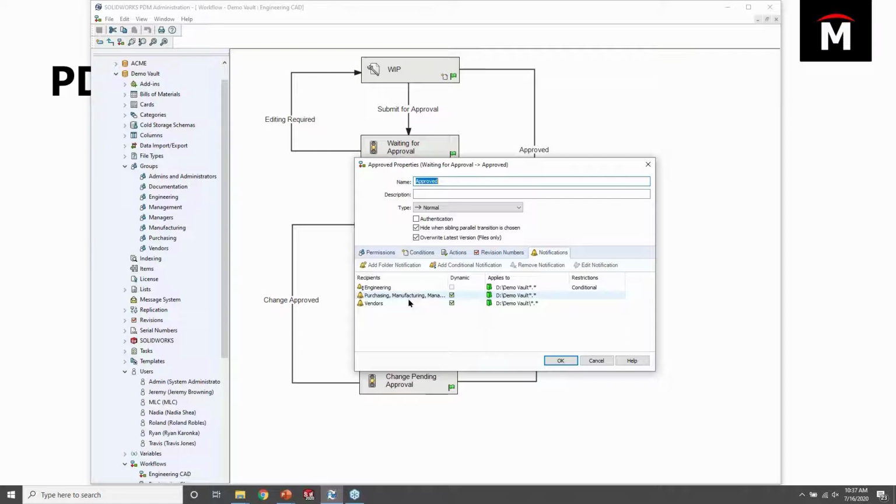And so it kind of becomes a scenario of the boy who cried wolf, where you're sending out these notifications and everybody's getting copied on them, and eventually nobody pays attention to them anymore. And so you've turned a technology that could be really effective into something that has no effectivity at all. So when you decide to implement notifications into PDM, make sure that the notifications are very deliberate and that you're only notifying people when they're required to take action. You'll find that that's a much more effective method than just putting notifications everywhere for the sake of notifying.